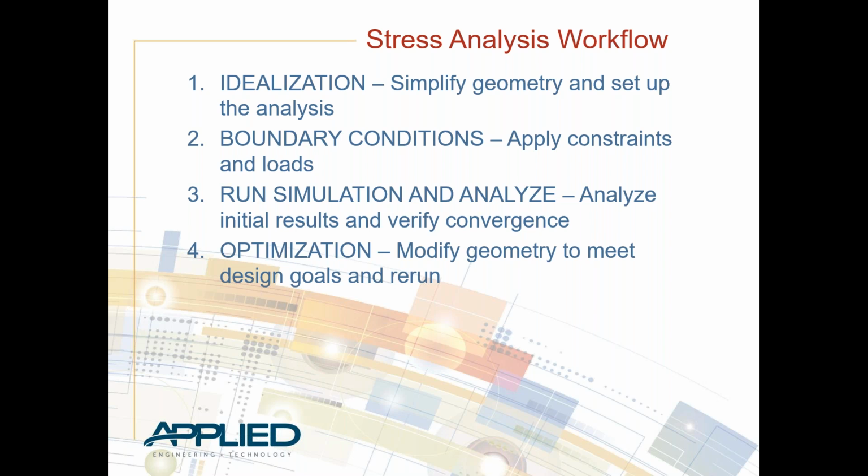We set up our boundary conditions as step 2. Constraints and loads are the main thing there. If you do have movement in your model, we can do that, but we may need to look at a different type of analysis to run, whether it be movement over time, or maybe you're looking at natural frequencies or modal frequencies. We want to make sure that as the model goes through a specific cycle, we see where the max loads are.